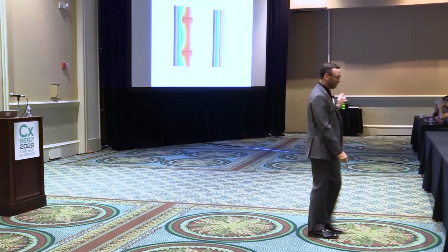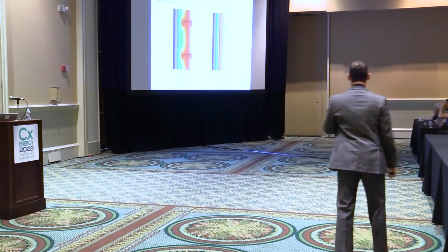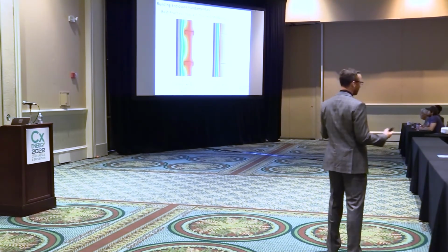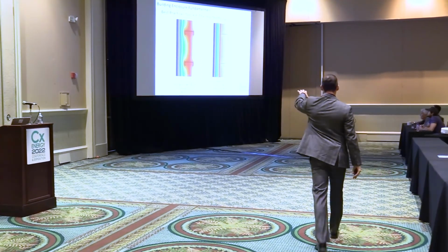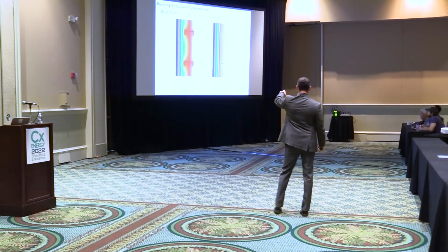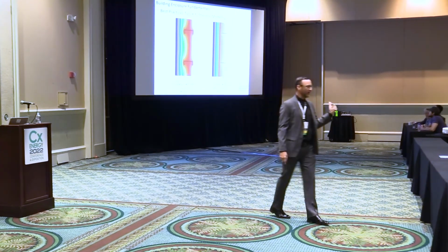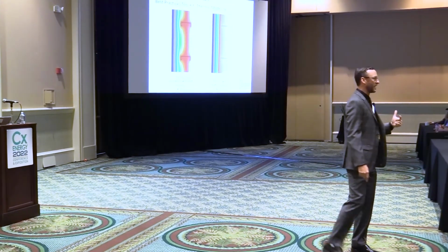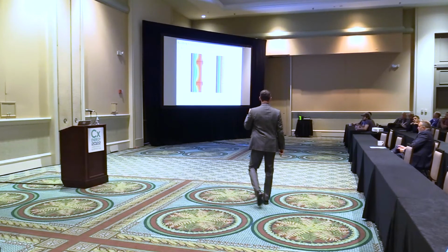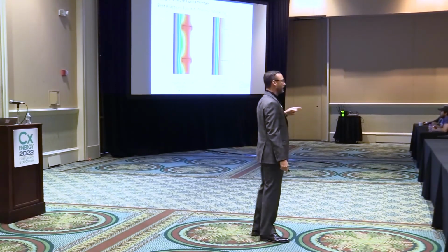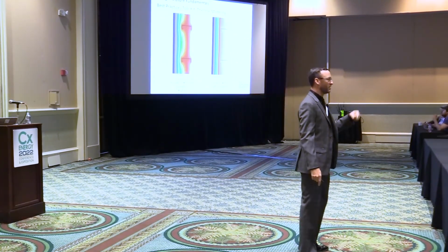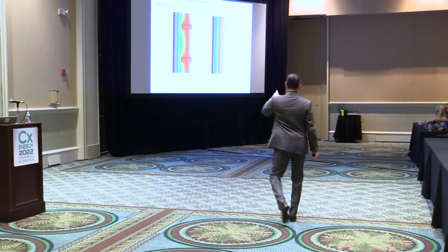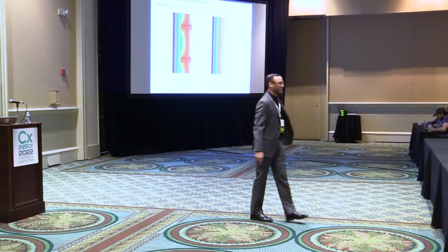Yeah, so this is simply an analysis of saying, okay, this building, and I'll use an example that might not be 100% applicable to this particular image. The energy code says that I'm in ASHRAE zone 4A and I've got to have R13 batt insulation plus R7.5 for my continuous insulation. But what would happen if we push that all to the outside?